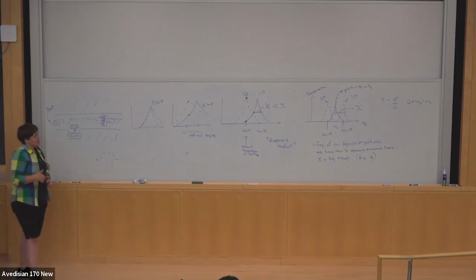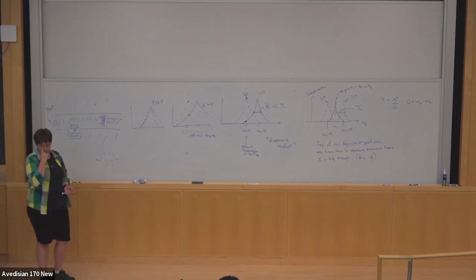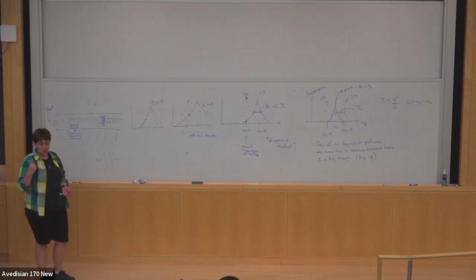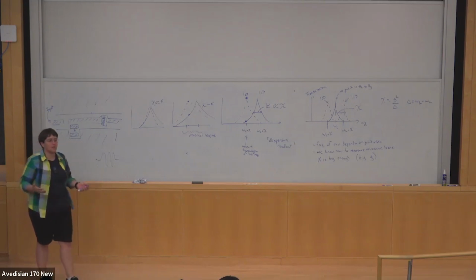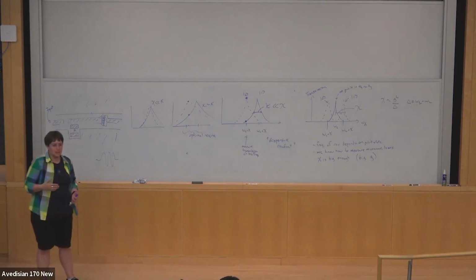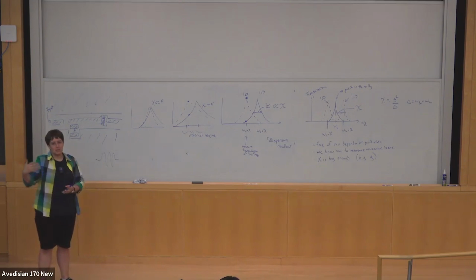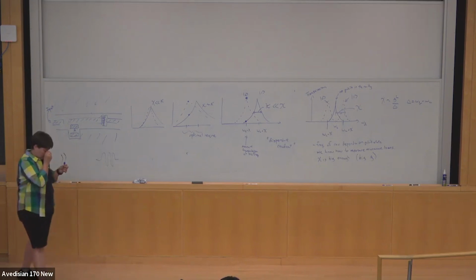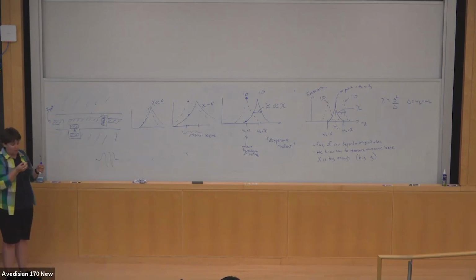But one of the things that happens is you can naively just start cranking up the drive power. If you're limited by your detection SNR, you just want to get more signal amplitude through in a shorter amount of time, so you crank up the drive power. And eventually when you do that, you start making transitions to unwanted states of the qubit.